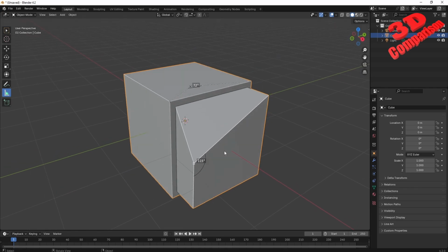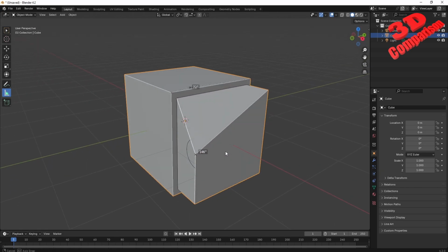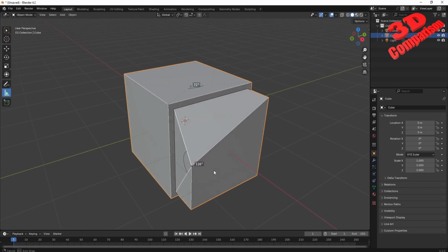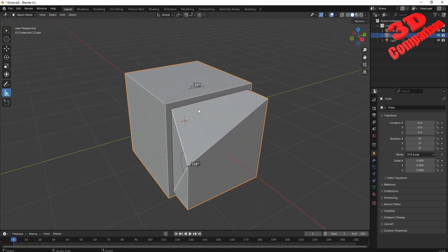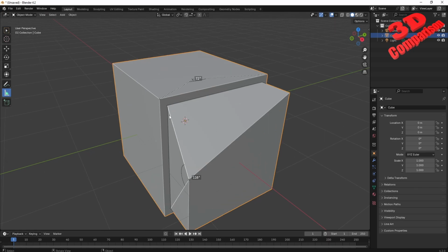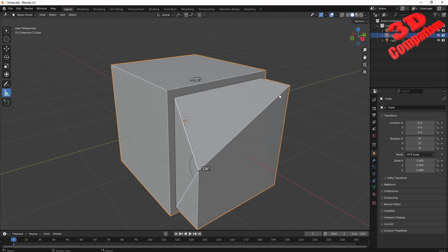So usually it's better to measure like this, so you can just snap your points around and you can see various angles over here. For example, maybe this as well. Also, if you want to add additional measurements over here, keep in mind that only the last one will be active. So currently this is the active one. As we can see, this is not a dashed line. The previous one is dashed. And if I will just draw a new one, the other will become dashed as well. And again, I have the possibility to snap this.